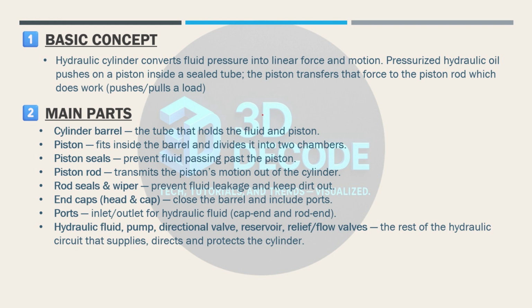Ports: inlet-outlet for hydraulic fluid, cap end and rod end. Hydraulic fluid, pump, directional valve, reservoir, relief and flow valves: the rest of the hydraulic circuit that supplies, directs and protects the cylinder.